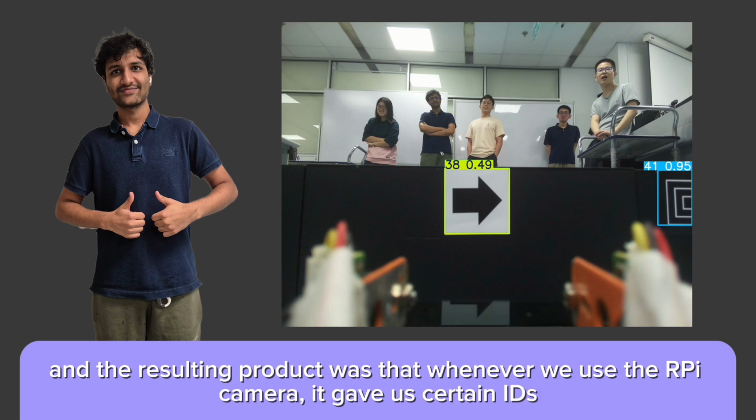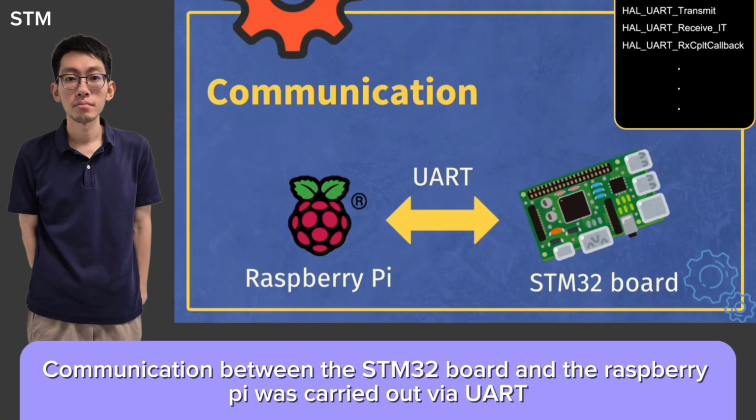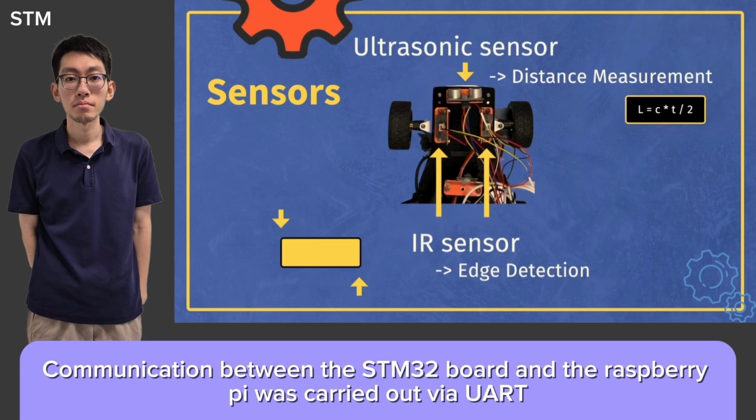And the resulting product was that whenever we used the RPi camera, it gave us certain IDs, which were then passed on to the algo team to decipher and use for the MDP robot movements. Communication between the STM32 board and the Raspberry Pi was carried out via UART.